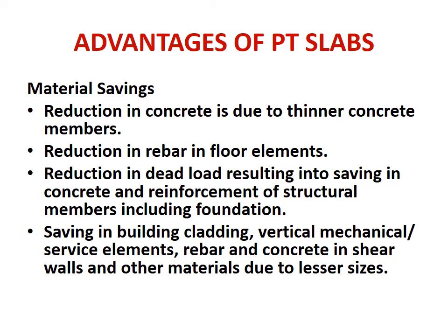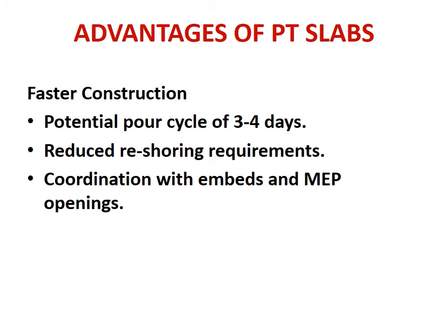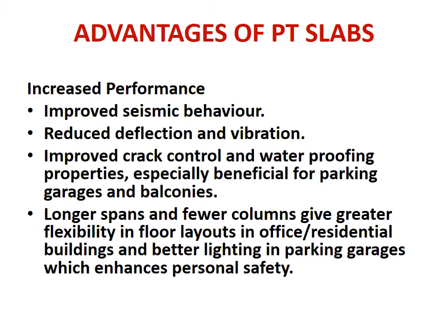including foundation. Then saving in building cladding because height can be reduced because of the higher headroom. Then vertical mechanical service elements, rebar, concrete, shear walls and other materials due to lesser sizes. And then construction is faster because the cycle is less. Then reduced shuttering requirement and coordination with embeds and MEP planes.